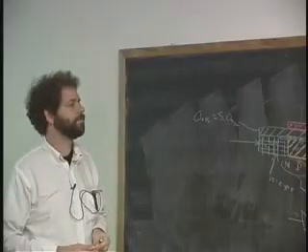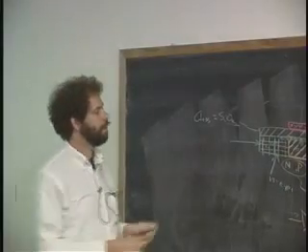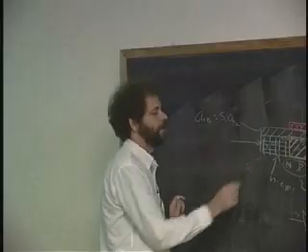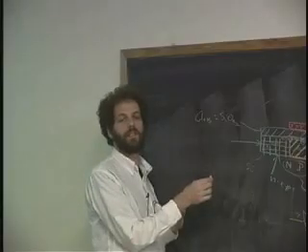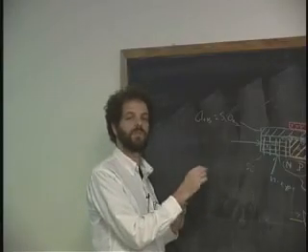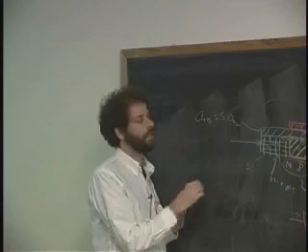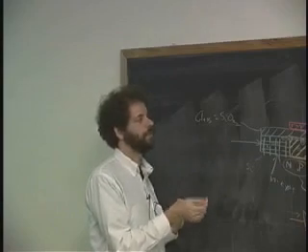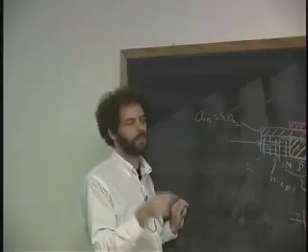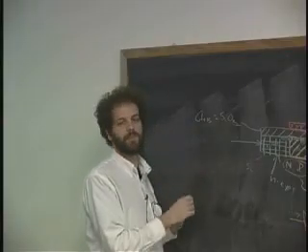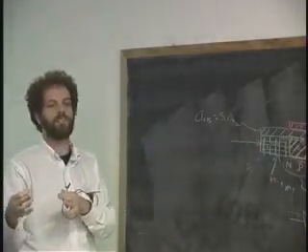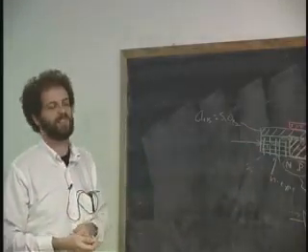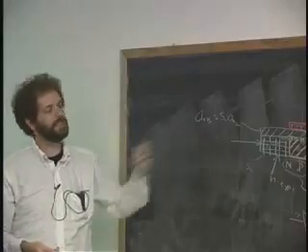Very, very small. What did you say the material of the p-type and n-type? These are both silicon, Si, except that they're doped a little bit. So silicon by itself is neither N nor P. And if you add a dopant to it, you can switch it from one to the other. And so arsenic is a dopant. There's phosphorus, gallium, thanks. And so you can change it from one to the other. But anyway, there's a whole bunch that you could learn about that, but there's no way I can teach architecture in 3 weeks and also do this stuff. So, okay, but this is basically the field effect transistor, and it's what we're going to use for this switch.